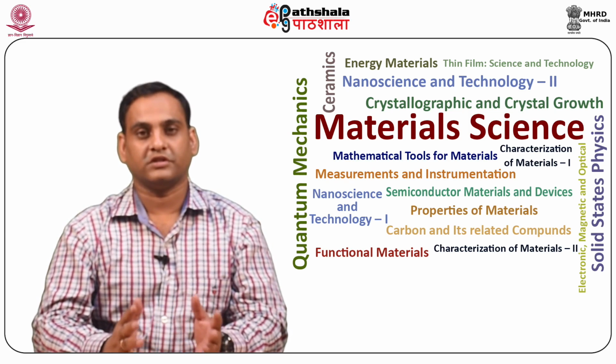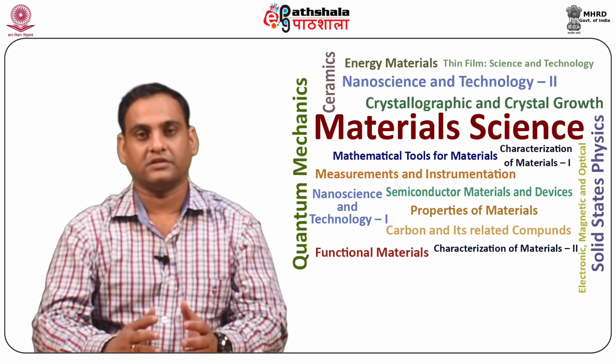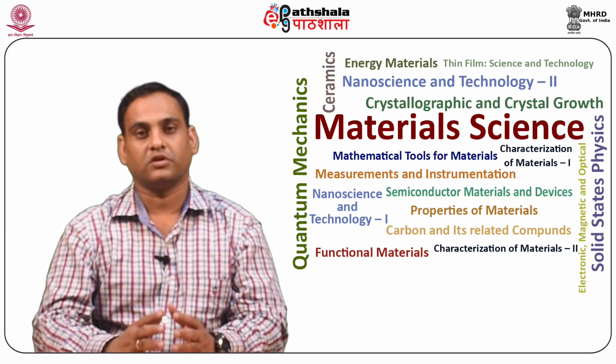There are four technologically important classes of magnetic amorphous alloys. One is transition metal, metalloid, early transition metal, late transition metal, rare earth transition metal, and alloys with group second A elements. Magnetism in LTM-ETM amorphous alloys has been extensively investigated from both fundamental and technological points of view.